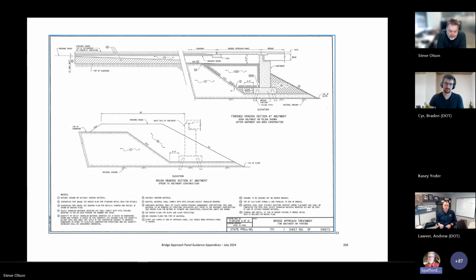We feel that the Wabo Genie joint and the DS Brown JP are both neoprene glands, and we would put those at the top of the list, but we don't put things at the top of the list on the APL. But inside knowledge, those would be at the top. The V-Seal and the Silicoflex joints would be our next choice. And it's totally 100% dependent on prep.